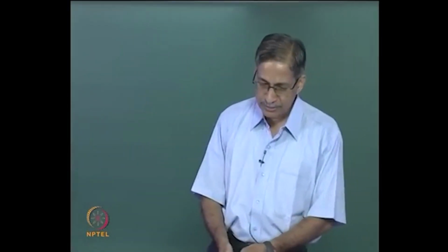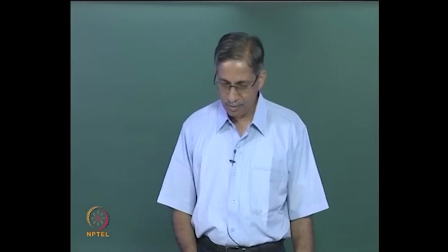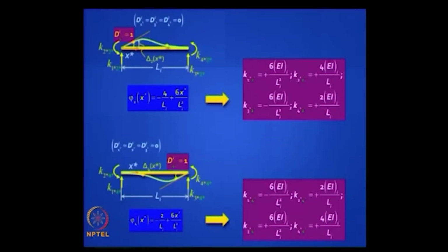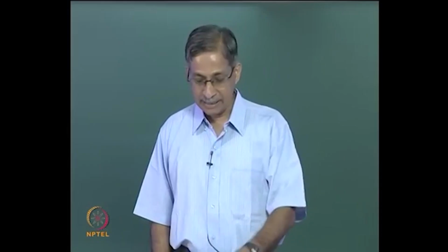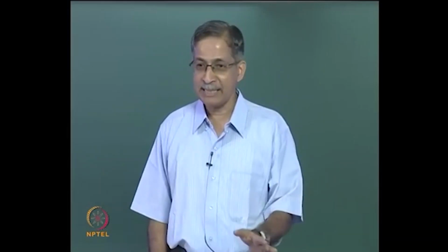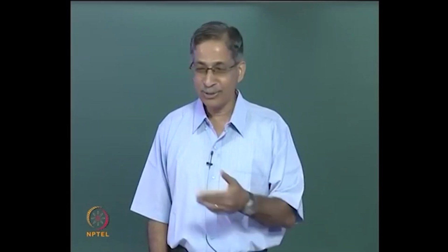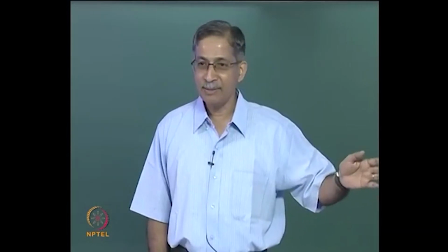And so you can do this derivation for all the 4 cases, you get exactly the same results. So we have done 2 alternative ways of deriving this element stiffness matrix. One is the force approach, physically we understand what is going on, we just write down those values. Second is we pretend we do not know statics and we know only geometry, we know only kinematics, we derive